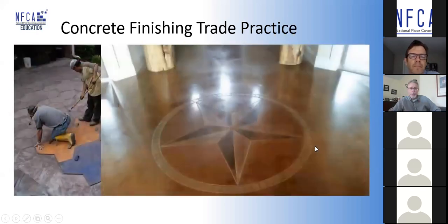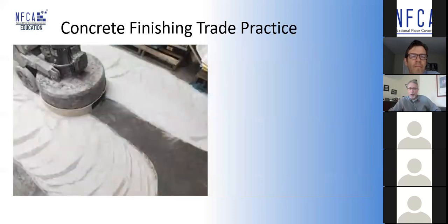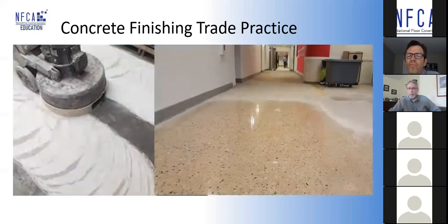Here we're dealing with either stamped concrete or stained concrete, highly refined surface finishes. We can also polish, giving what a lot of architects are calling these days rustic terrazzo, basically grinding up the concrete surface and making that the finished surface by mechanically polishing with very fine grit diamond pads to create a floor finish out of the concrete itself.